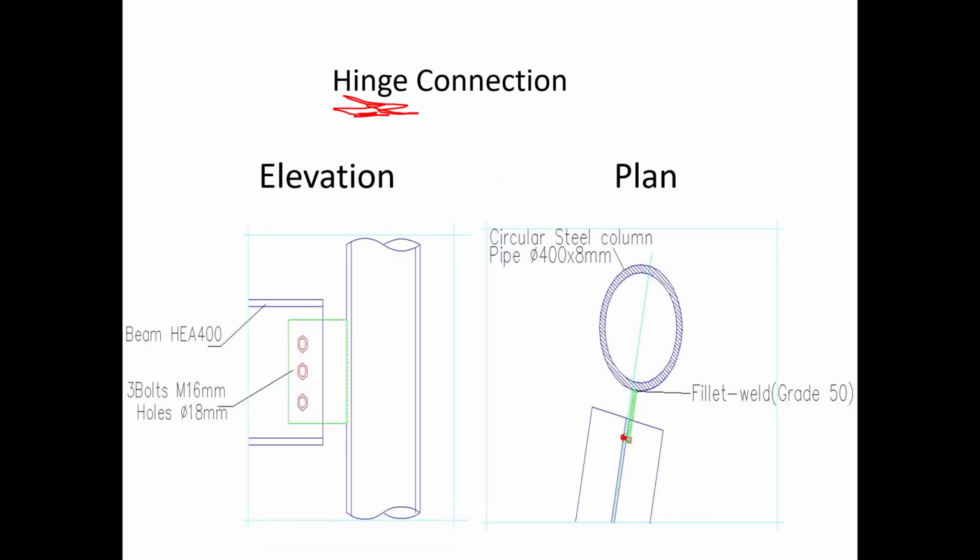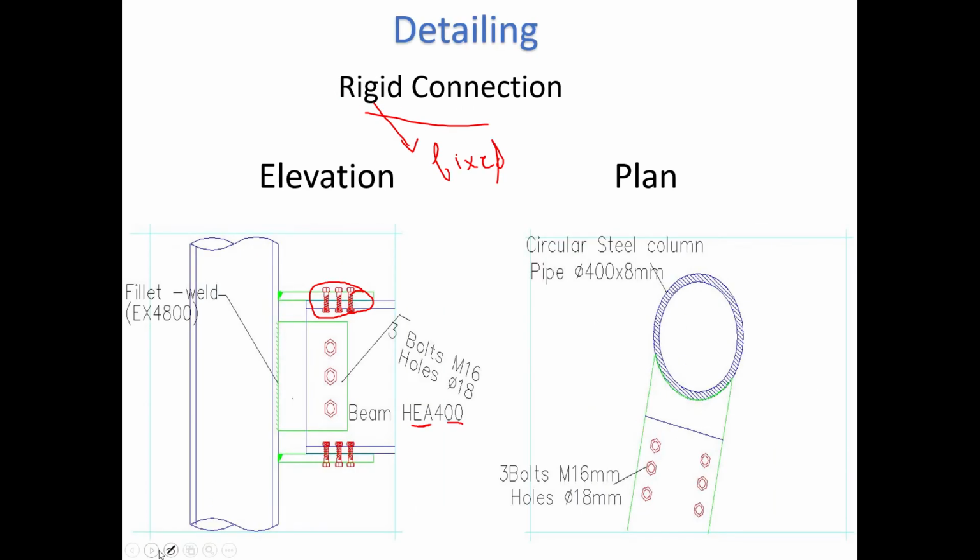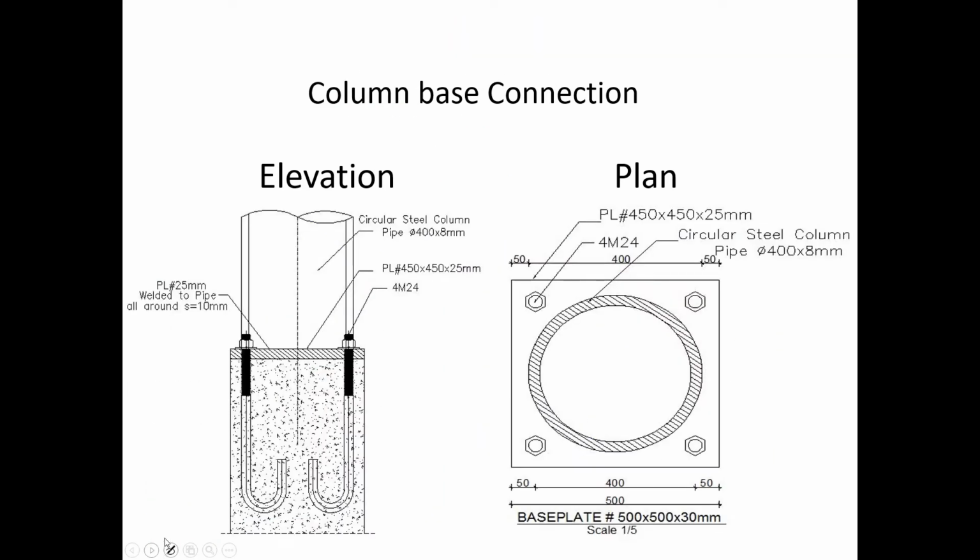Hinged means we have only X and Y forces as reactions. Here we have a moment in addition to X and Y. Okay, here we have the column base connection, the connection between the column and its base.